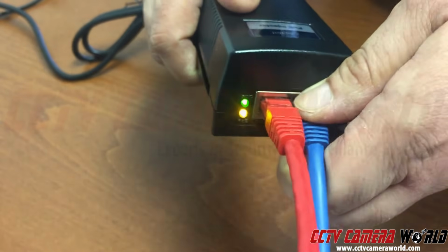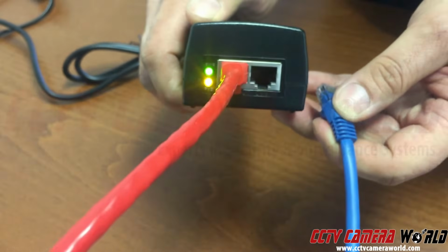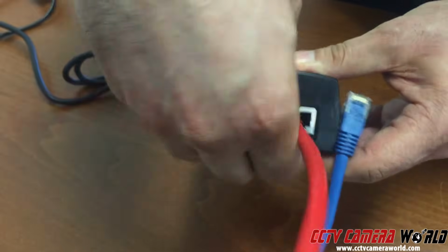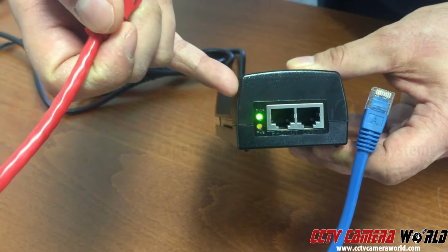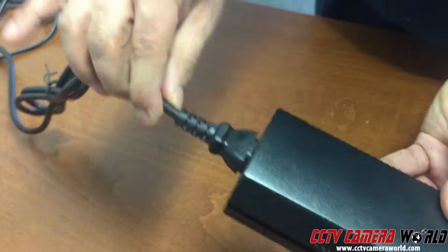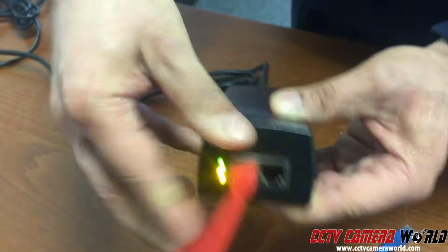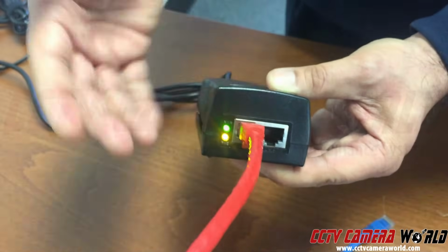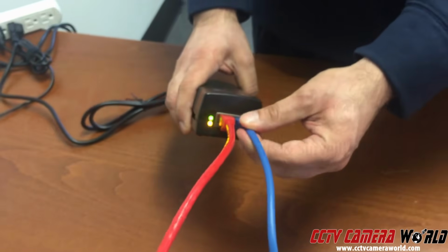So if I get a good connection, I'll see both lights illuminate on the camera. So you know you have a good cable. If you just connect the PoE injector and you want to know if it works, you'll have a green light as soon as you connect it to power using the AC outlet on the back. And then when you connect your camera, the amber light will pop up if it's actually getting data from the camera. Unfortunately, there's no LED to show you if it's communicating with your laptop or not.